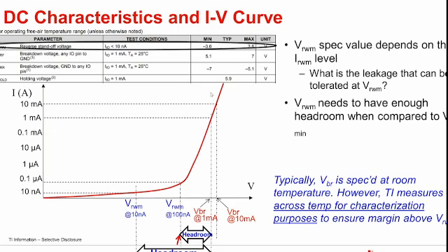It's important to note for ESD devices the difference between DC and transient events. So the DC characteristics for the ESD device are for it to remain invisible on the line. This is where you get the VRWM, which is the reverse standoff voltage, which shows what signals can go through with very low leakage for it, and that will not be affected by the system.